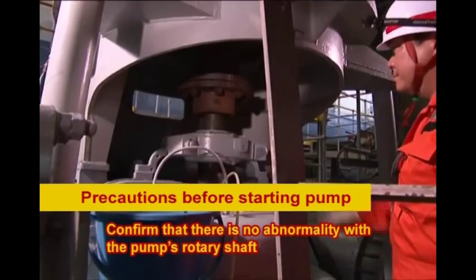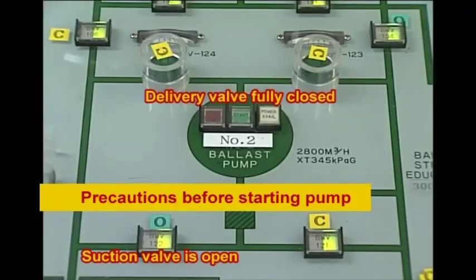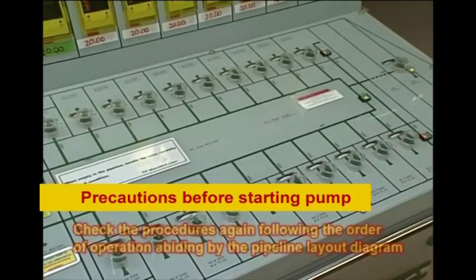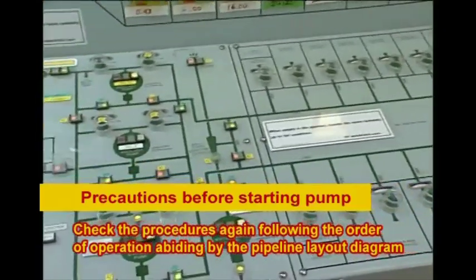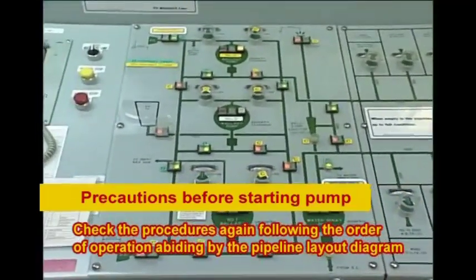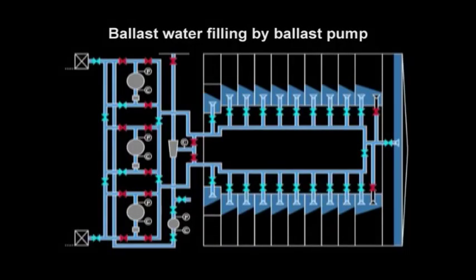Confirm that there is no abnormality with the pump's rotary shaft. Confirm that the suction valve is open and the delivery valve is fully closed. Just before starting the pump, check the procedures again, following the order of operation, abiding by the pipeline layout diagram. Start the ballast pump.